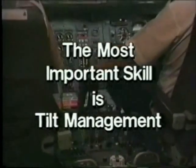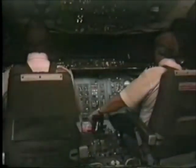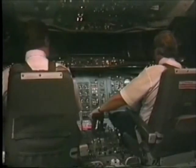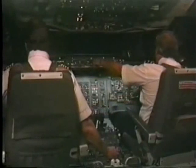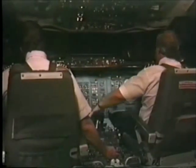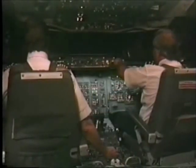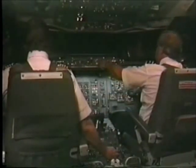By learning to use the beam to observe the ground in good weather as often as possible, you will become familiar with its reflection characteristics. Having gained this familiarity, you'll be able to adjust the tilt angle of the antenna to make valid assessments of weather conditions. Remember, weather radar is a tool pilots have, much like extended vision, that provides significant warning of hazardous weather. Use this tool wisely, and it will add to the safety of your flight.